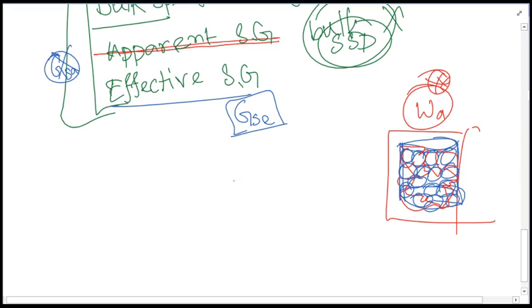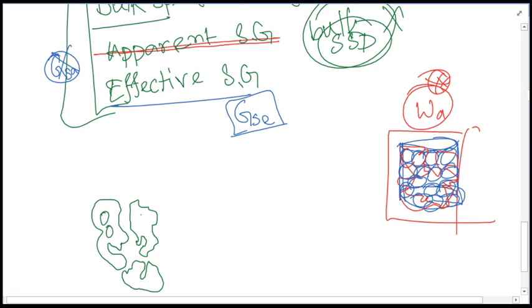After 24 hours, the water will penetrate through all the permeable pores in these aggregates beyond the bitumen, as bitumen cannot go up to the furthest point of the permeable pores that water can reach. So if these are the aggregates, although some impermeable pores will be present, that is not our concern, the bitumen will penetrate some portion of this.